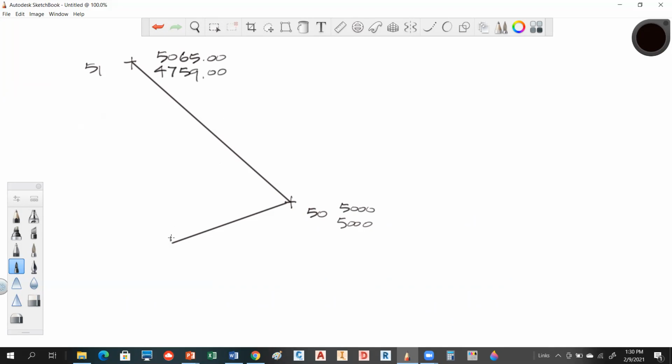So we have a manhole over here on the set of plans. This manhole has a coordinate on it, so we need to stake it. A lot of times people will use numbers for different purposes. Like we would call all of our points 300 on our project either sanitary sewers or catch basins or manholes or something. And then you might use series 200 for buildings and series 400 numbers for parking lots. So people kind of do it that way to keep everything straight.